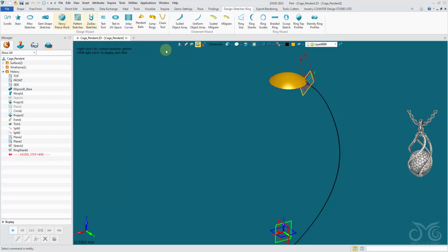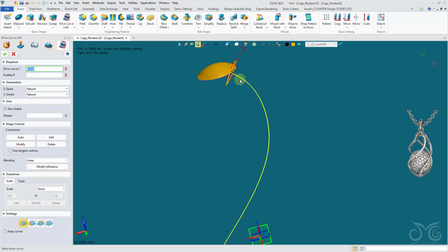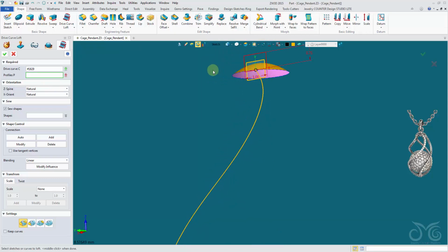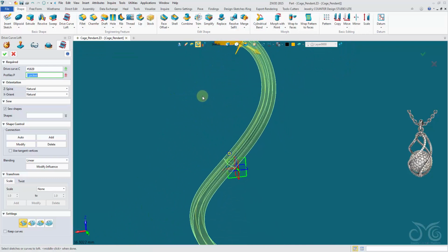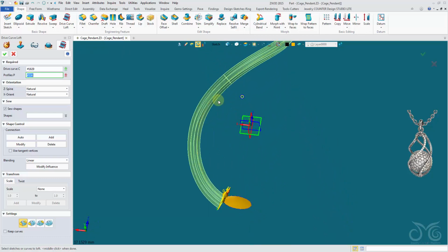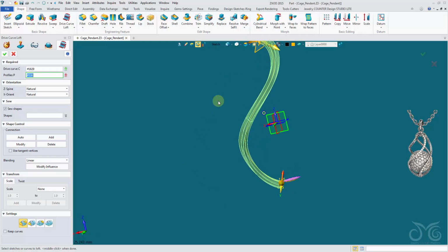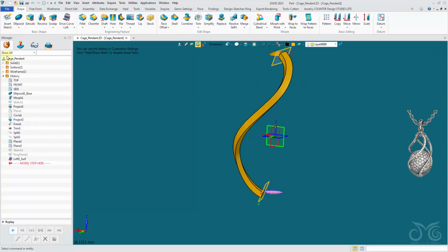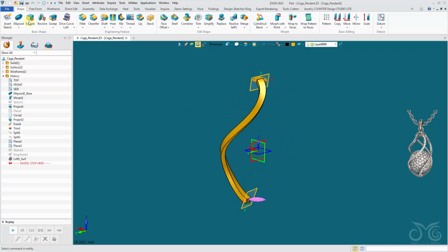Now let's perform a driving curve loft of these sketches along this path. Now if you have a background in Rhino, the drive curve loft is the same as the one rail sweep. Okay, so the drive curve loft, we pick our curve to drive along, so this curve here, our profiles, picking sketches, remember we need to pick them at the same point, so picking on the lower left hand corner of that sketch, so we pick on the lower left hand corner of this one. There's our sweeping preview. Okay, we'll confirm the operation. Save our work.